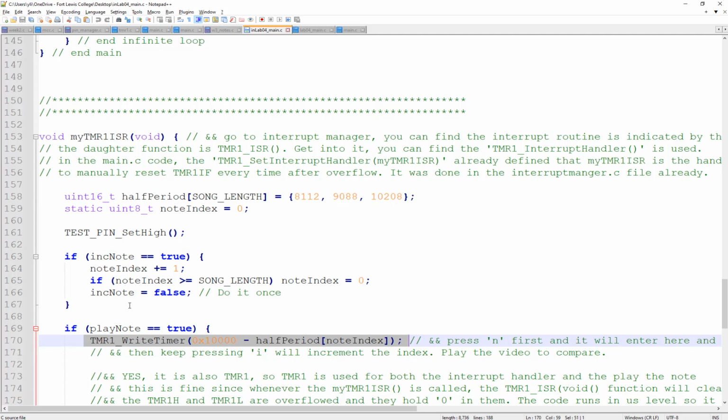What's really happening? You've got two Timer 1s, right? Timer 1 for the interrupt routine triggers the interrupt, and then you get another Timer 1. You are writing a new value to it to wait for the flag to be turned on again. Is it still serving your purpose to play the note? And how? You just have less of the clock registers.